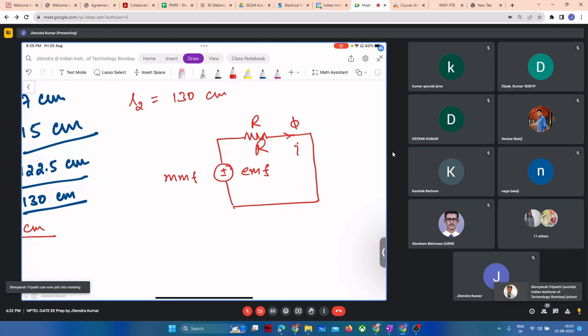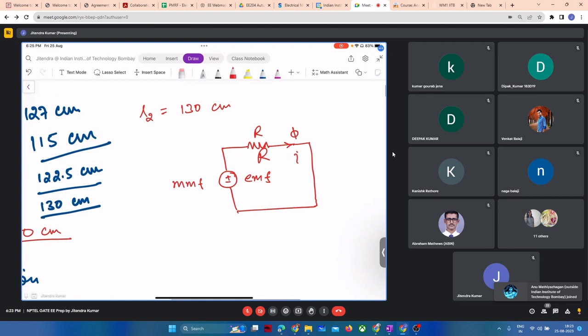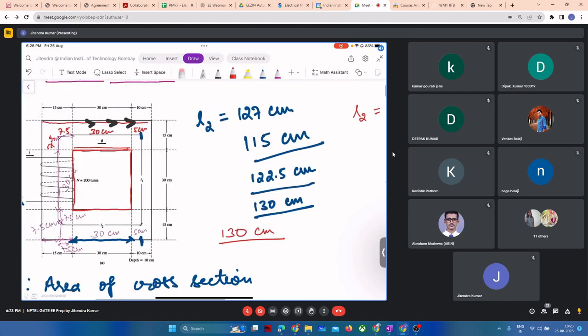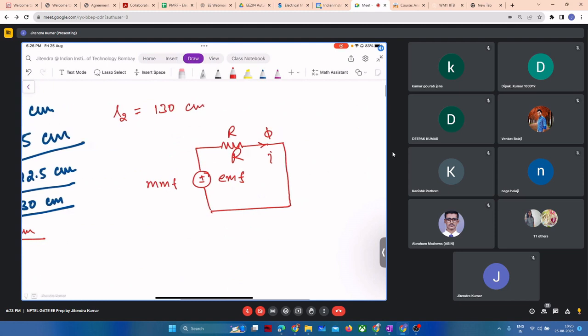So we utilize our knowledge of electrical circuits and apply it here in magnetic circuits, and we see that MMF is the source of flux, whereas in an electrical circuit, voltage is the source of current. We have some voltage source that is able to produce a certain current in a wire or in a closed circuit, and in an electrical circuit we have wire resistance, whereas in a magnetic circuit we have the core, which we call reluctance.